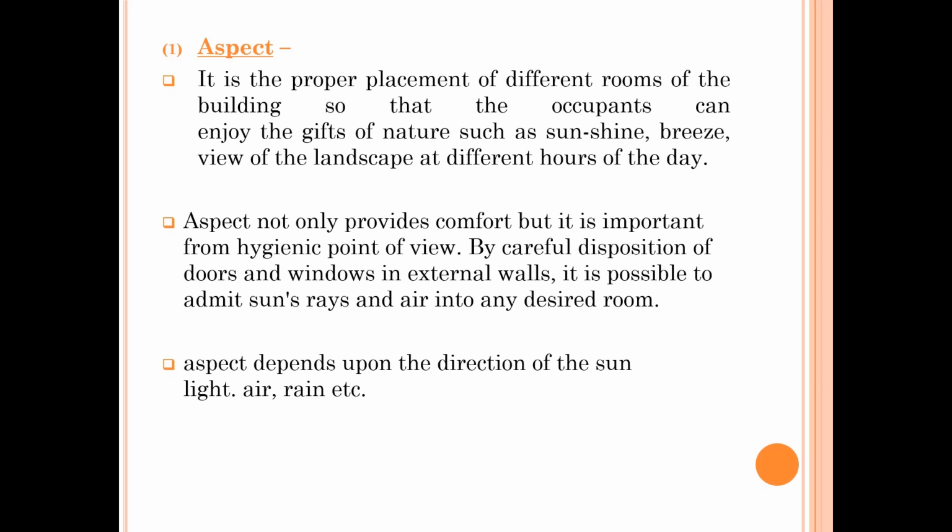Aspect not only provides comfort, but it is important from the hygienic point of view also. By careful disposition of doors and windows in external walls, it is possible to admit the sun's rays and air into any desired room. So this is important: careful disposition of doors and windows in external walls, so that we can have the sun's rays and air into the desired room. So aspect depends upon the direction of sunlight and air and rain, etc.